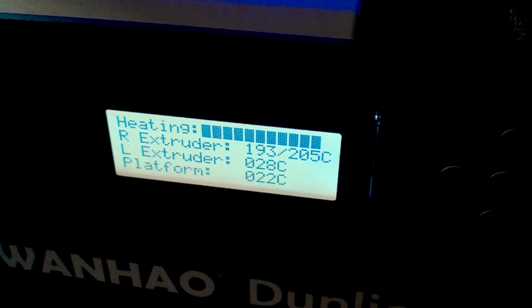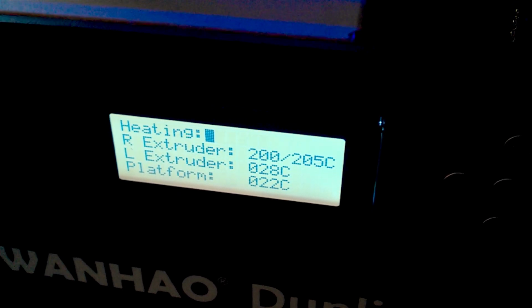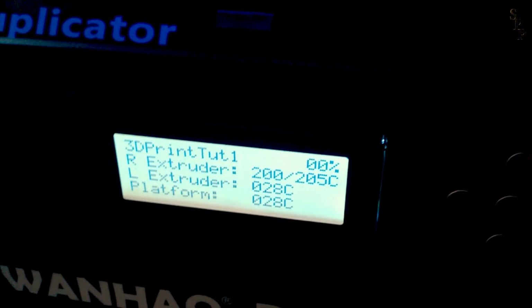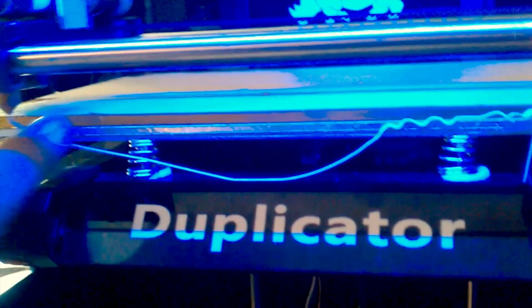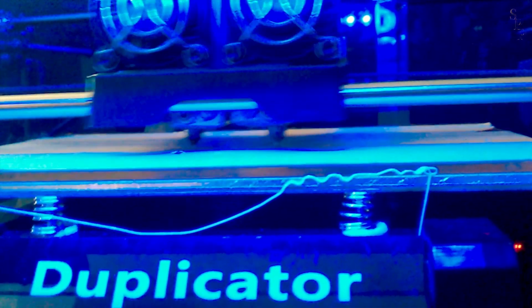In general, you want to print toward the lower end of the ideal print temperature so that the extruded plastic cools as quickly as possible. So you can see there's plastic starting to come out. Because I compiled this in MakerWare, you can see it thinks it's on the plate and it was actually off the end. It's not a real problem at the moment. And there it's drawing the first circle, or attempting to.